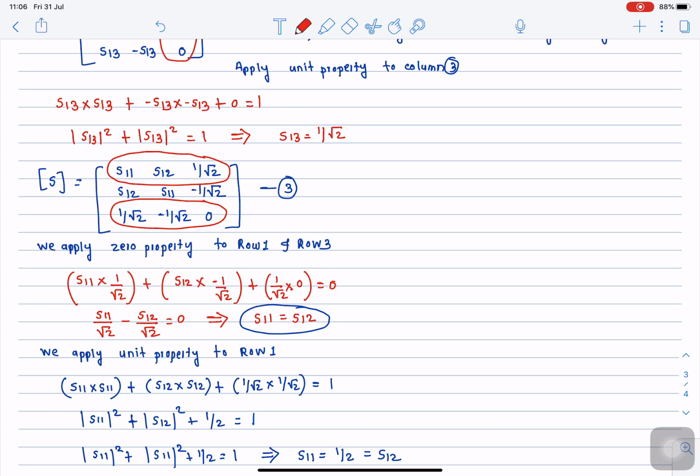As an application as a tuner, a movable short can be placed in the side arm. The input is connected to one of the collinear arm ports and the output is extracted from the other collinear port. The susceptance offered by these junctions depends on the depth of insertion of the side arm. So if we change the susceptance, this change can be utilized for impedance matching operations.